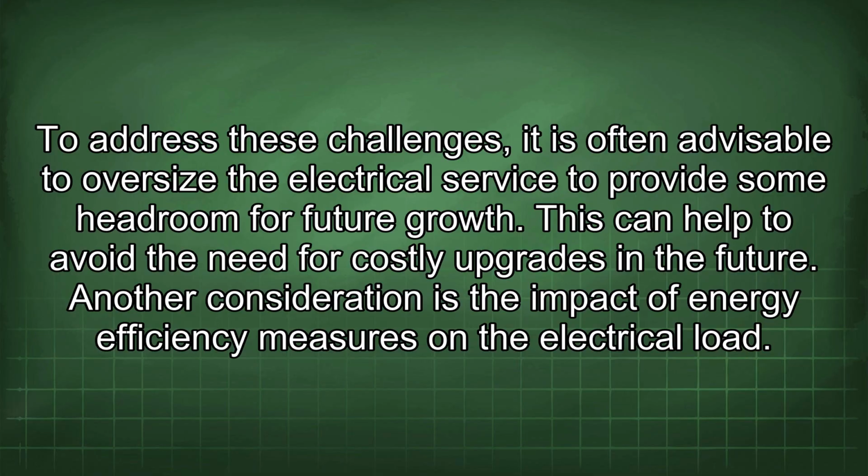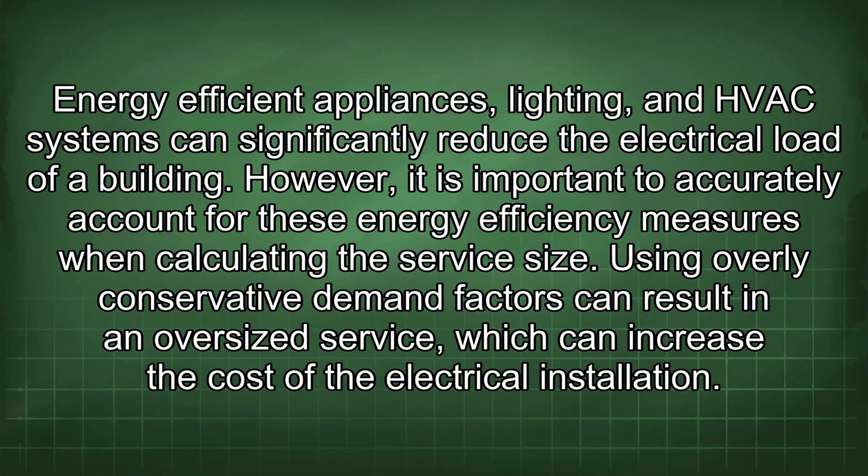Another consideration is the impact of energy efficiency measures on the electrical load. Energy-efficient appliances, lighting, and HVAC systems can significantly reduce the electrical load of a building. However, it is important to accurately account for these energy efficiency measures when calculating the service size. Using overly conservative demand factors can result in an oversized service, which can increase the cost of the electrical installation.